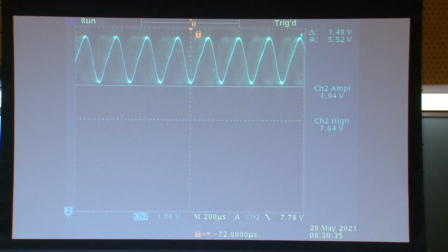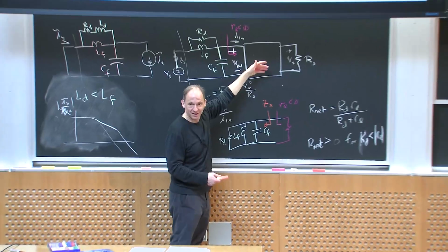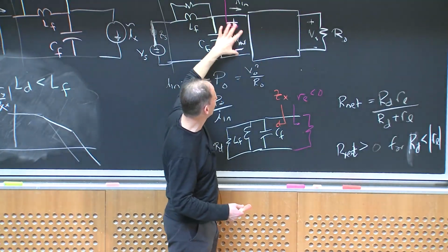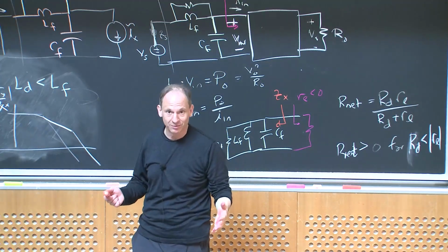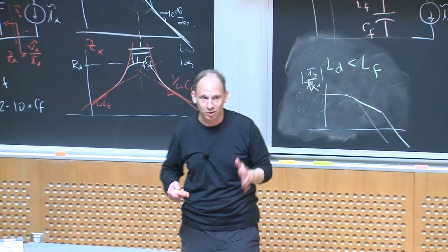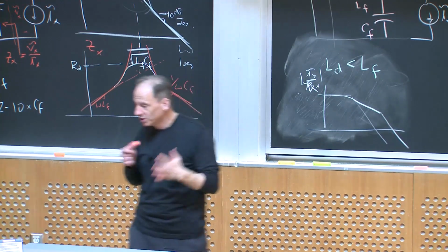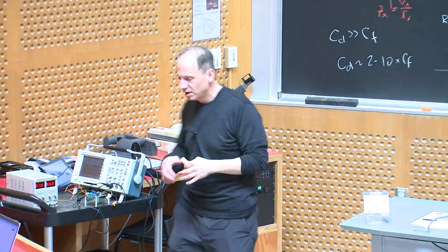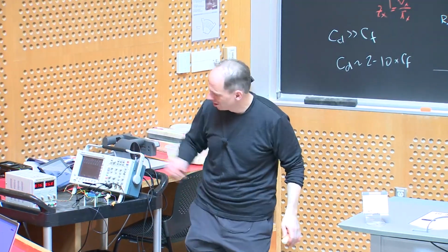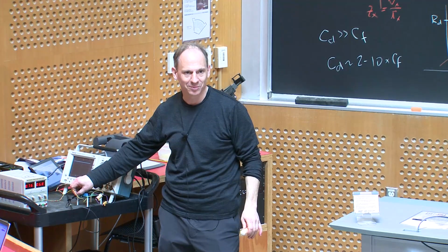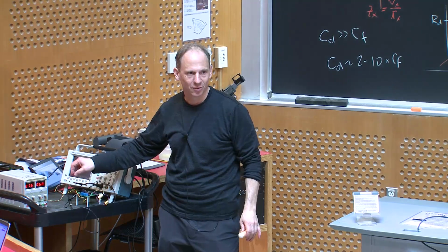You say, well, I can live with that. I don't care. Well, it depends, right? Sometimes you hear a lot of noise. This is just with the converter at some value of load. But imagine we're trying to draw current varying near that frequency. It would go really crazy, right? So you really can't tolerate this kind of thing. And you would see this in the converter response at the output and so forth. So you really do have to seriously account not only for the fact that you need a damped LC, but you need to account for the negative input impedance of the converter in order to get acceptable response. Any question about that?